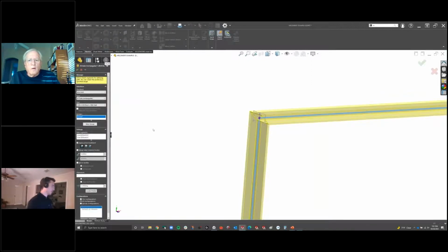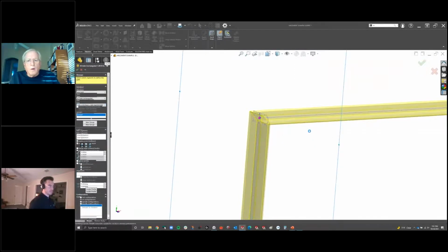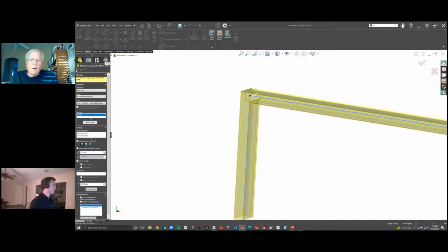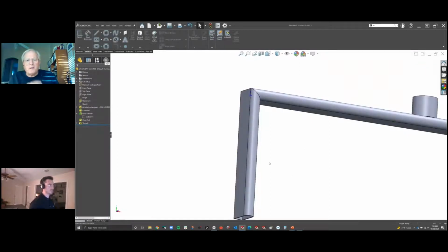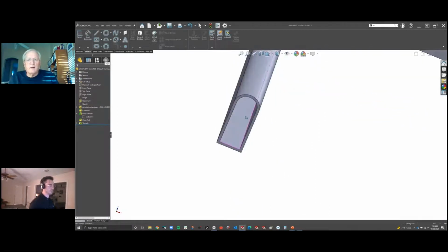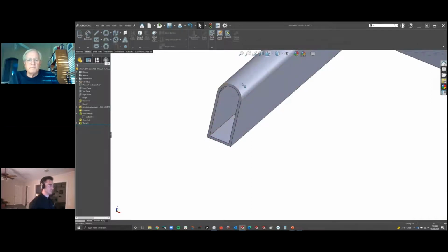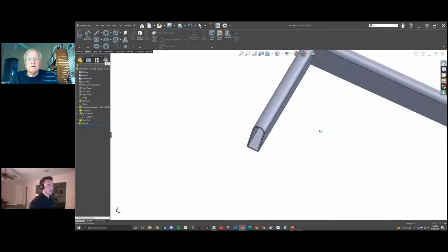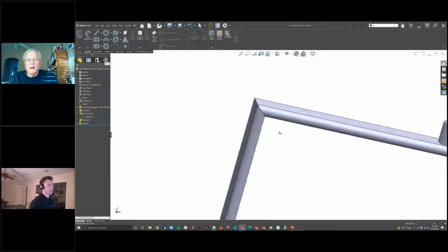Edit feature. So right here in selections, this is in the size tab. I'm going to drop down, and I modified this tube with the modifier round on the end. Just going to open that up, select that, and then the Weldment tool is going to do all the work for me. So instead of sketching out that custom profile or trying to modify an existing Weldment, I just created a new profile, and you can see SolidWorks did all the hard work for me because I was able to insert that custom profile. So that is briefly how we do a custom profile for Weldment.